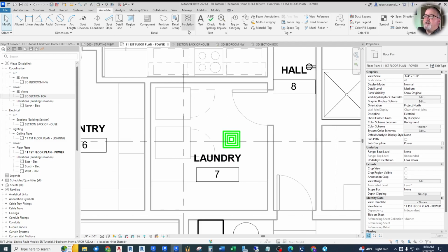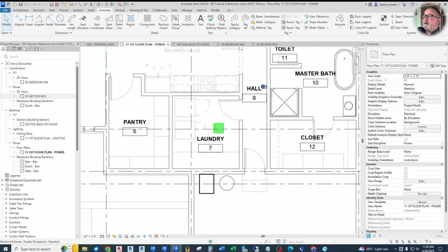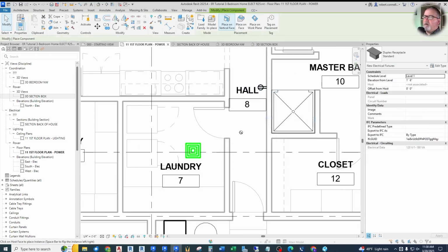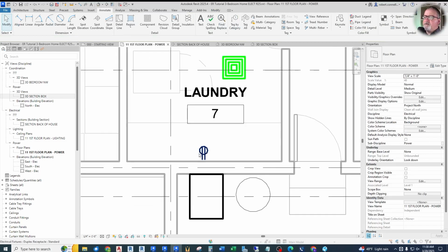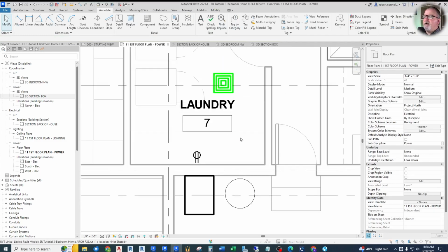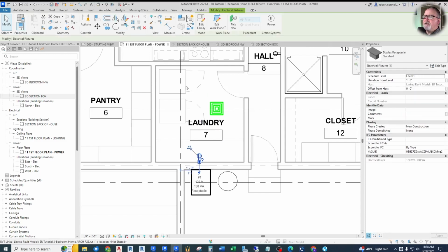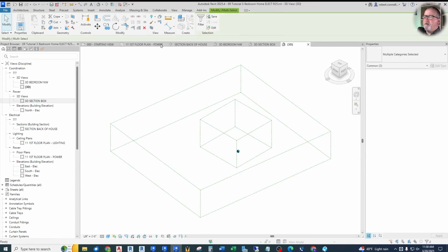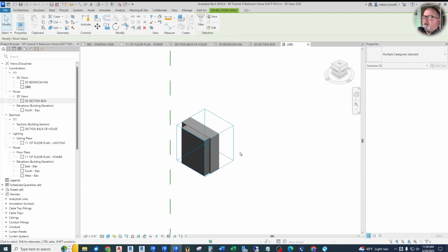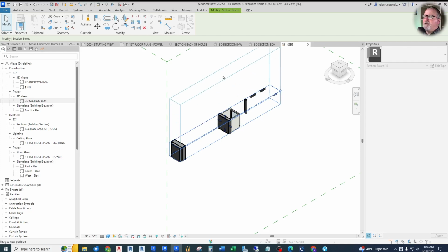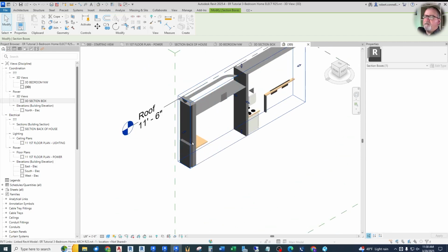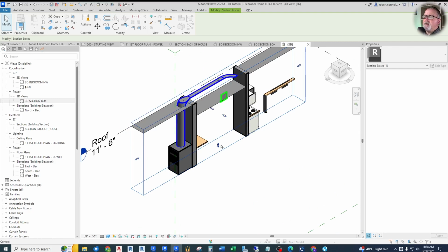So I'm going to do the section box here again. Let me put a receptacle in here, right there. Now, this receptacle, I may want higher. I want above if this is a cabinet. Let me just click this and do that section box, and we'll see what we have here. Again, it just does a tiny little box that we need to show. Now, we've already turned the section box on for our 3D view, so it sticks that way now. But we do need to spread this out to see what's in here.